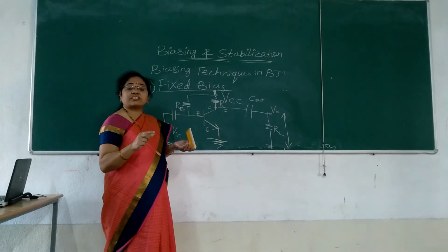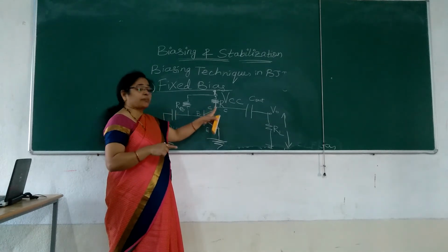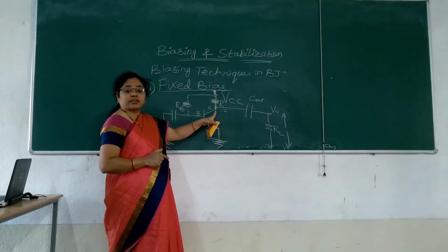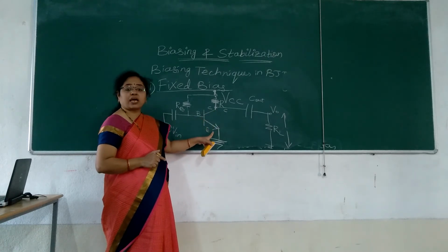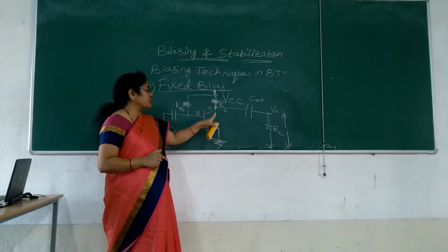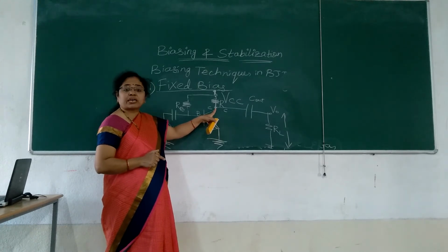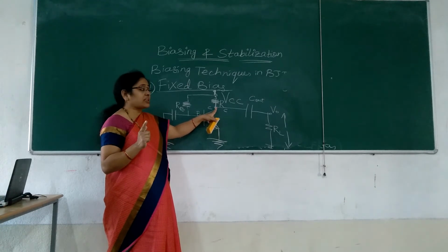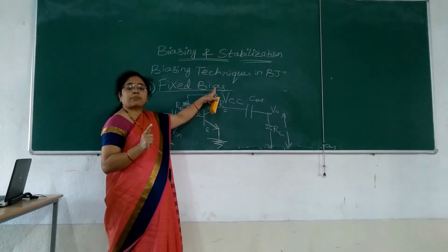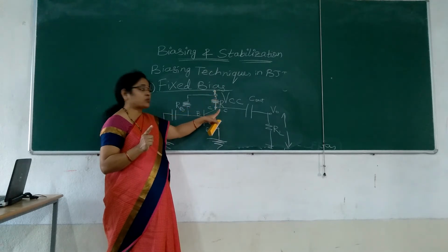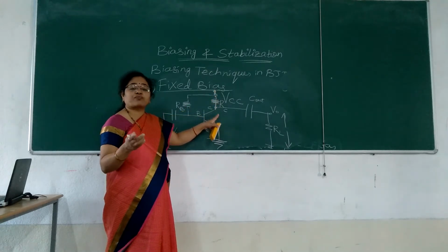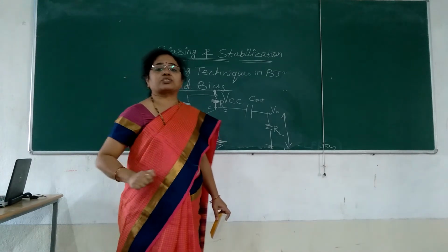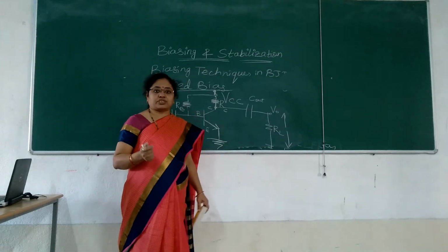We will now see whether the output side, the collector-emitter side, is reverse biased or not. This is another point. I have taken an NPN transistor, so this is N. N should be connected to P in order to make the reverse bias. So this N is connected to the positive of the battery. Positive is connected to N, hence it is reverse biased. So we have fulfilled the criteria that the input side is forward biased and the output side is reverse biased. Biasing is accomplished.